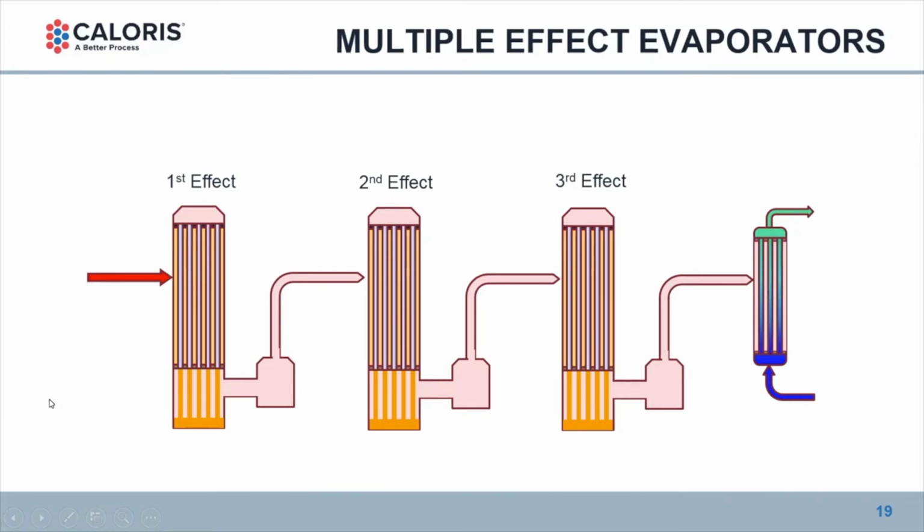And in round numbers, for a pound of steam coming in, you can evaporate 3 pounds of water in a 3-effect evaporator, and you have the equivalent heat rejection into the cooling tower as that steam coming in. It's energy in equals energy out. Now, what's happening here is each time we go to a deeper vacuum, specific volumes increase.